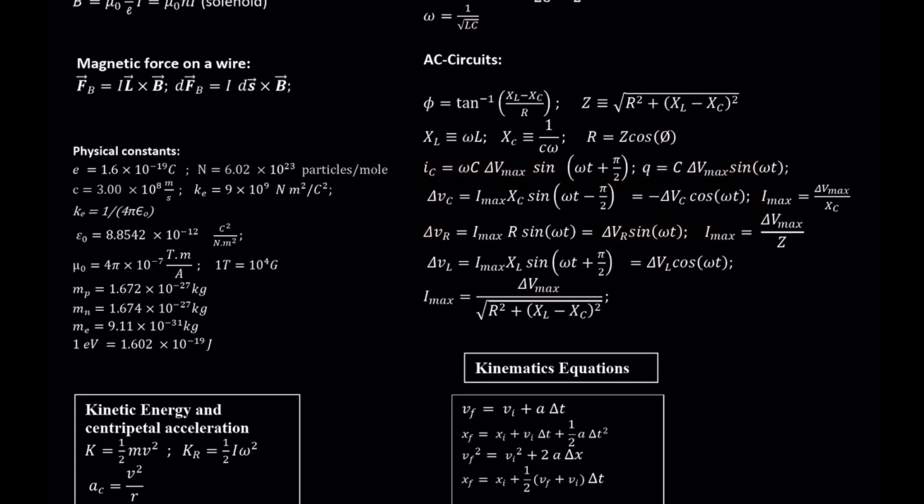So just to quickly take a look at all of the first equations, we just saw that the resistor had this form here. Let's take a look at the inductor. We have, again, an I max, this little x, and again, a sine with the omega t, but this time a plus pi over 2, which is different from the minus pi over 2, which is different from the nothing on the resistor. So keep in mind these differences. And then let's quickly take a look at the second half of the equations. You can see the resistor remains like this.